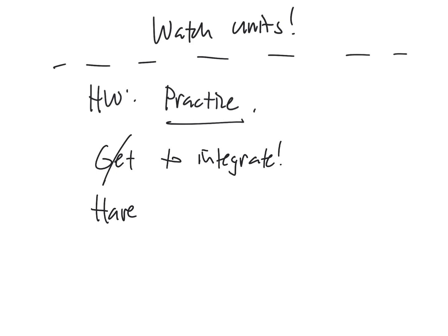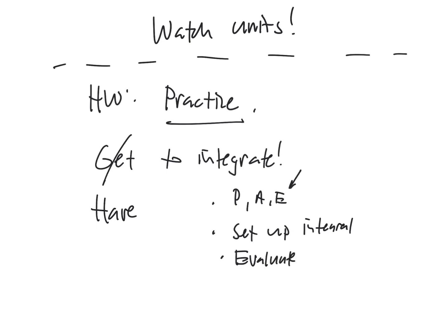Now that's going to be the only example that we're going to do for the case of varying strain, but they're all similar to that. To summarize, ask yourself which things vary. Is it P, A, or E? Then you have to set them up. Frequently they'll be given. We could have what's called a functionally graded material that would have an elastic modulus that varied with X. That's possible. But in any event, you need to set up those values, then set up the integral, and then finally evaluate. So they've all got a similar sort of flavor to them, and they're not too bad.